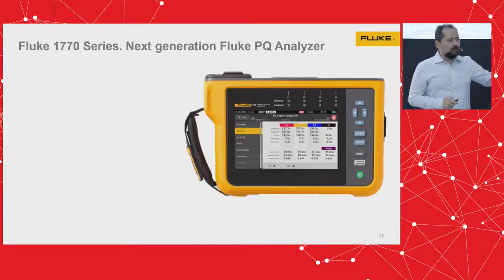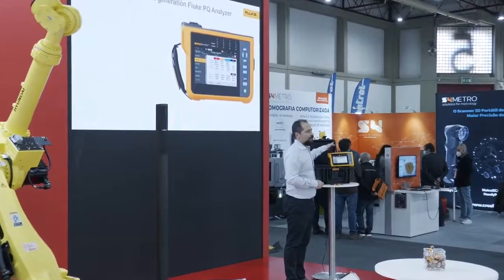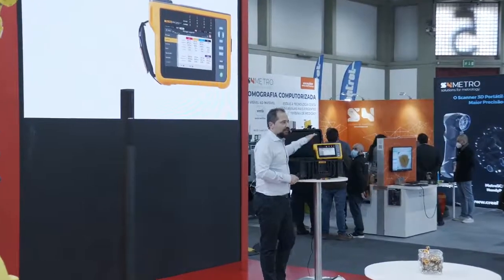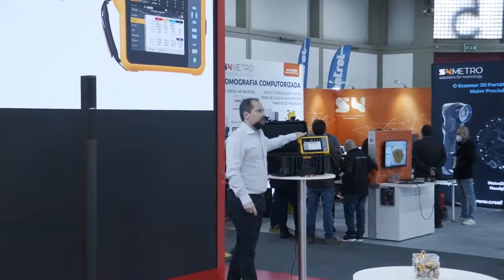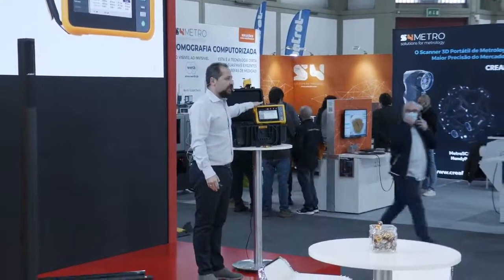A few words about our latest release, the 1770 series that you can see here, which is the most powerful power quality analyzer we have so far, capable of analyzing harmonics up to 30 kilohertz, sampling signals up to 20 mega samples per second. That's for transients, where we have really fast signal changes. It has plenty of communication interfaces: Wi-Fi, Bluetooth, GPS for transient synchronization, Ethernet, and so on and so forth.